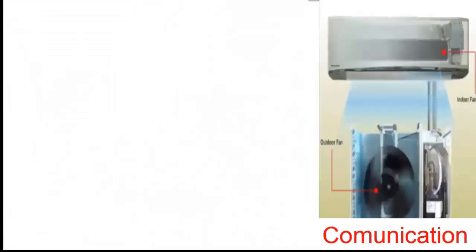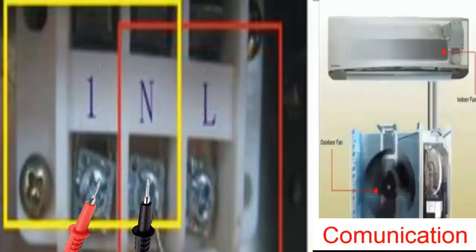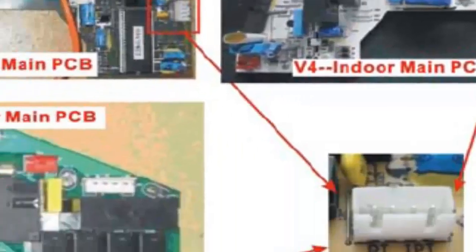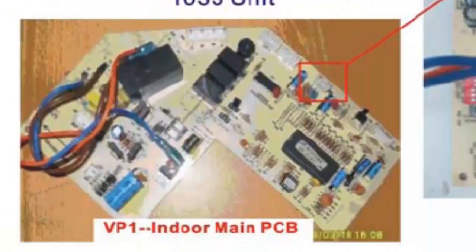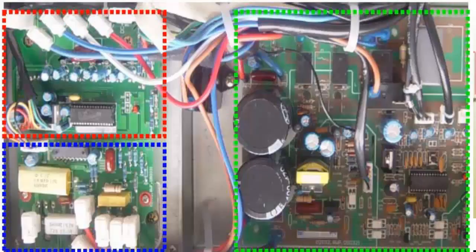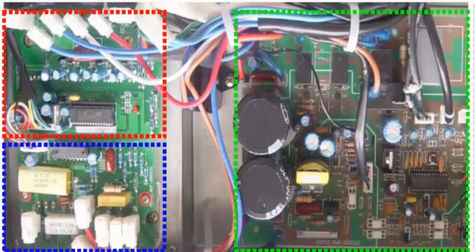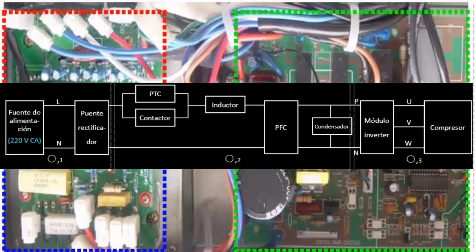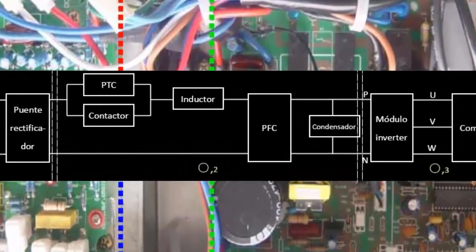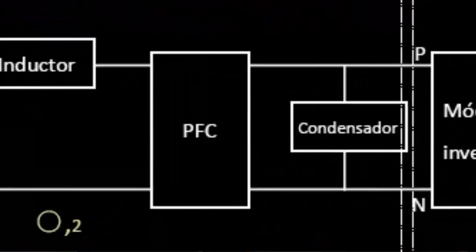8. If there is no voltage change between the N terminal and terminal 1 in the previous step, first focus on or replace the main indoor PCB. If the problem persists, the issue is in the outdoor power supply. 9. Check the PFC circuit located in the outdoor unit. Test the pins of the rectifier bridge, fast recovery diode, and IGBT transistor for faults, shorts, or damage.